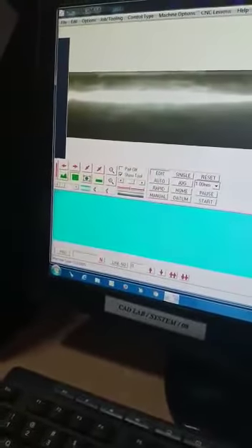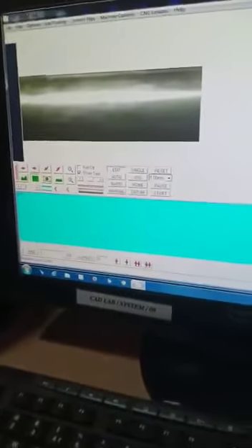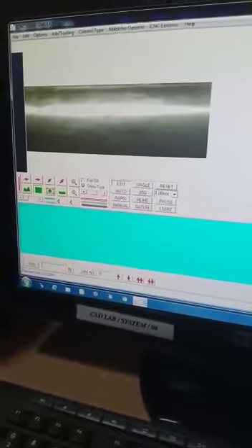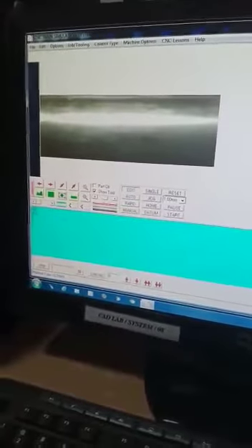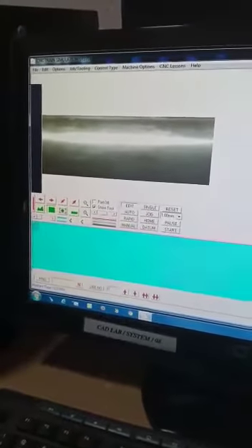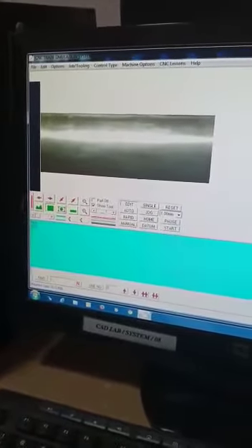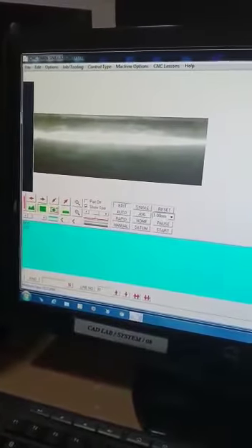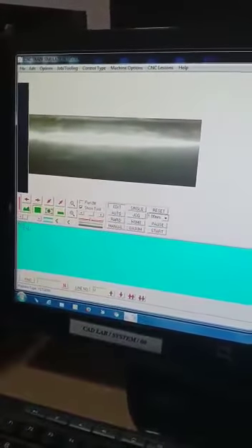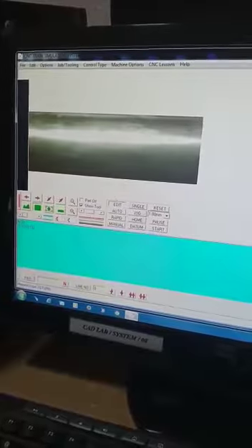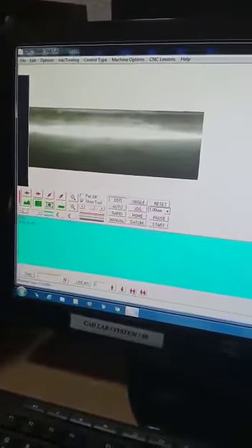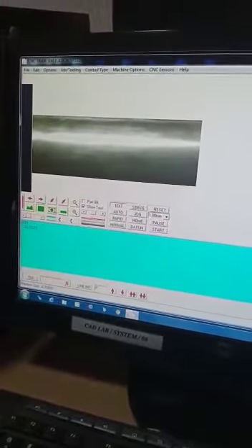Here you have to type N00 first of all, and then enter. Now you have to type what you have written in the observation note, block by block. For example, G00 is the positioning. With every entry you have to put a gap. So one gap, then X0 gap, Y0 gap, and for positioning, the position is